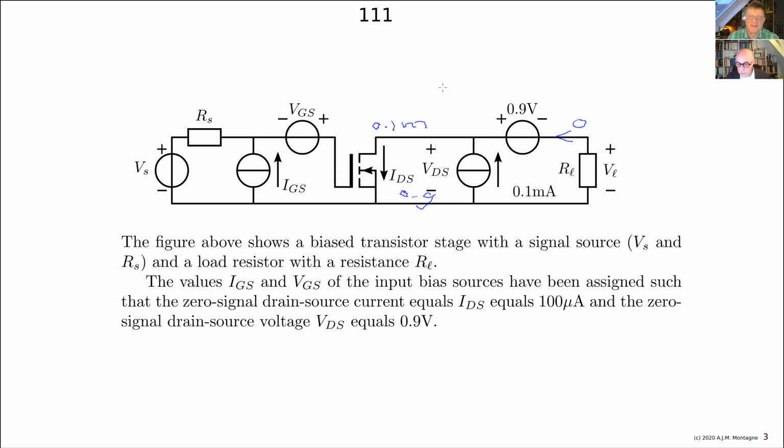Okay, so what you have to do is nothing else than just apply Kirchhoff's law and be very consequent in it. A positive product of branch current and branch voltage is dissipation, a negative is energy delivery. It's as simple as that.